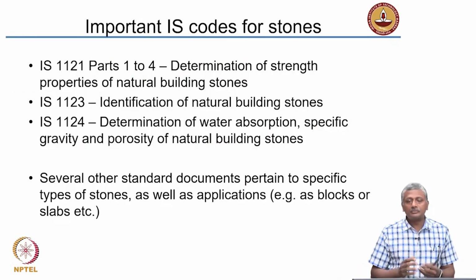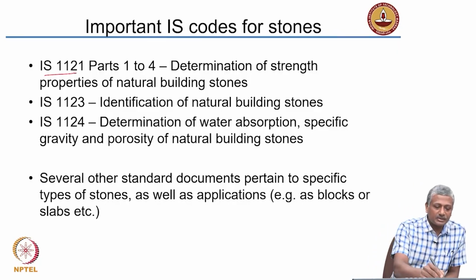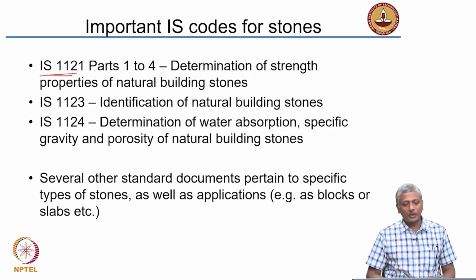Okay, so now what do we need to identify whether a particular stone is good for construction or not? Once again, the Indian standard has been devised to help us out in this regard. So, there are standards within this group of standards in IS 1121 parts 1 to 4, which talk about determination of strength properties of natural building stones.